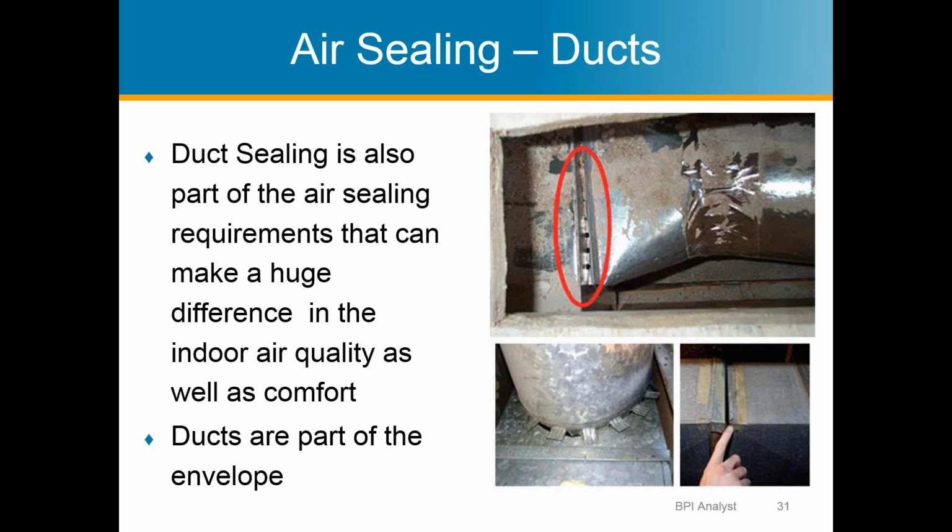So that's certainly energy efficiency, that's one. Depending on where the leak is, if it's a return leak, it could be sucking in air from the attic where those rodents hang out, or just sucking in insulation from the attic. So it makes for worse indoor air quality inside the house. So don't forget the ducts.